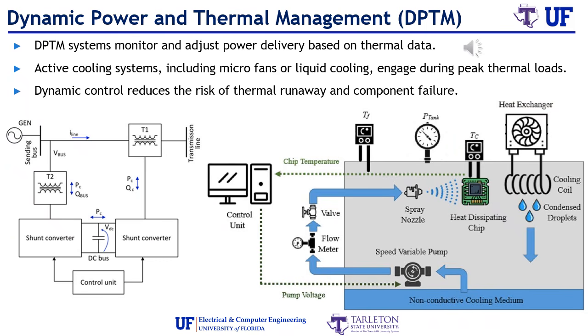Dynamic Power and Thermal Management (DPTM) coordinates sensors and control mechanisms to keep devices within safe operating ranges. Sensors monitor temperature, voltage, and current, feeding that data into control algorithms. In laptops, DPTM shows up as the CPU or GPU throttling briefly when a heavy workload raises temperature. In servers, it might distribute workloads across sockets or racks to spread thermal stress. In embedded systems, it can control fans, pumps, or valves, activating them only when needed to save energy.